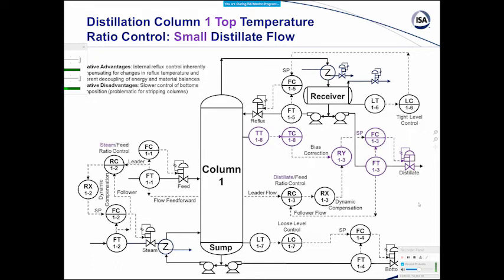And I encourage you to go to the Control Talk column that I've done with Siegfried Nino, who's a protege of Shinskey, to show how he used relative gain matrices to find out how to decouple that and deal with the interaction problems you have when you're trying to control two temperatures. Basically it's called dual temperature composition control, and you're getting into a lot of interactions then. So here we don't have so much an interaction problem, but we're trying to pair up